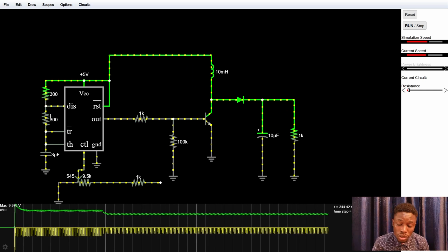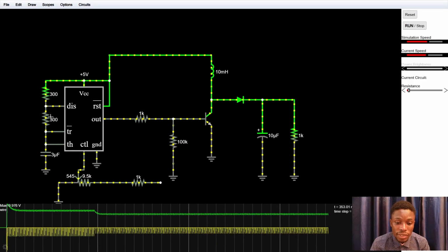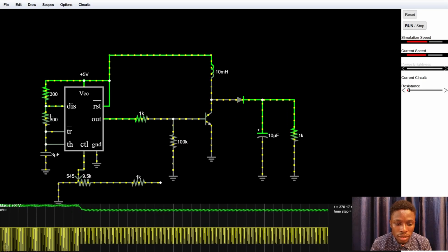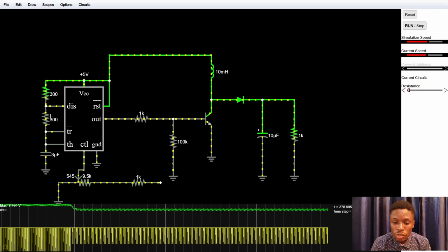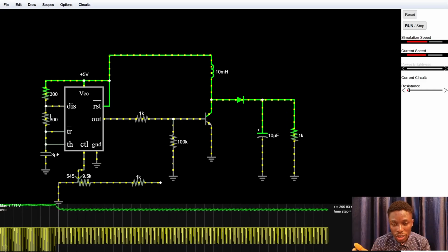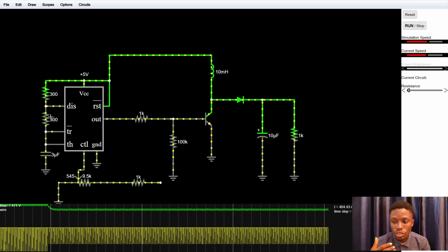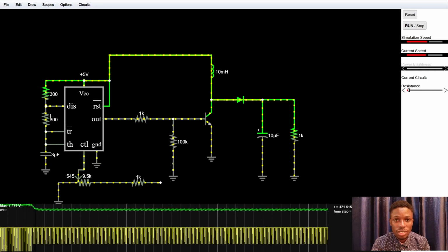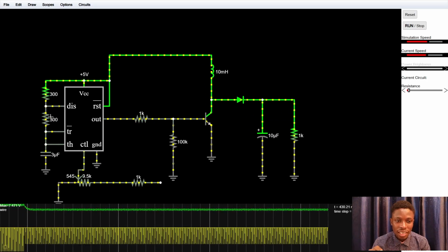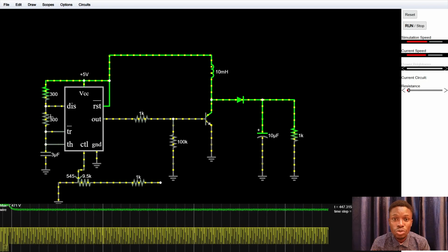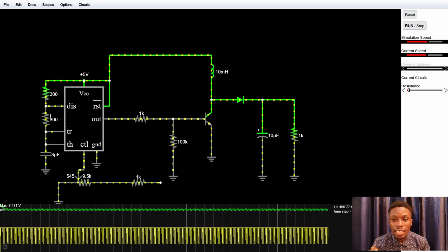Now, most switching regulators use frequencies above the sound frequency. The reason for that is simple, so that you will not be hearing the noise produced by that oscillation audibly. So if you've ever had some chargers make a high frequency pitching sound, they didn't take cognizance of the frequency of oscillation they used in their design.